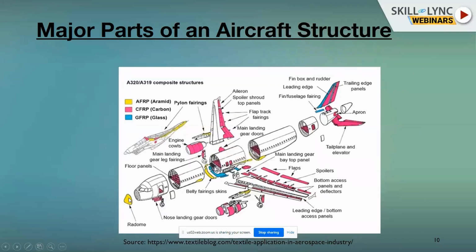It should be conical shape. So we, the structures group, design it. The radome should withstand 4 lb of bird strike load. If it is something like a vulture, which is beyond 4 lb of load, then it is sure going to fail.